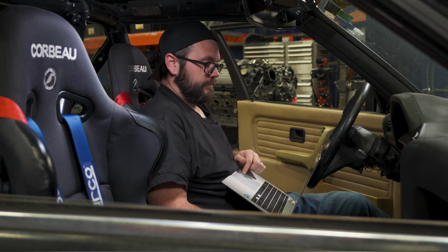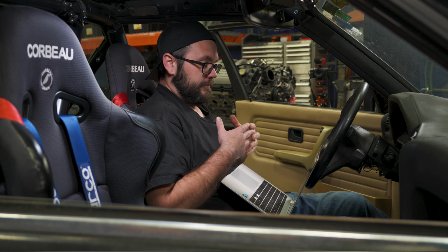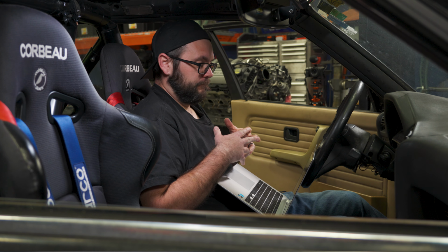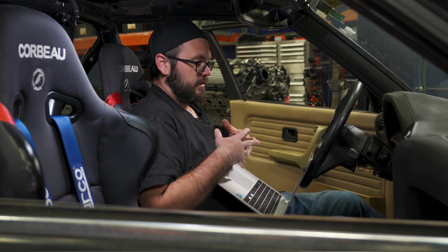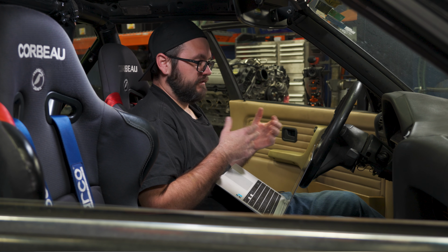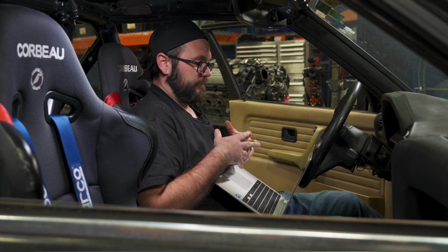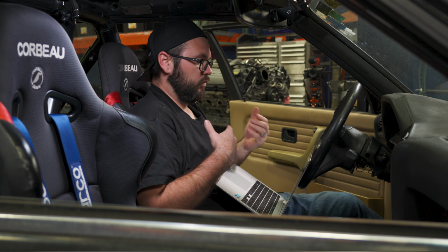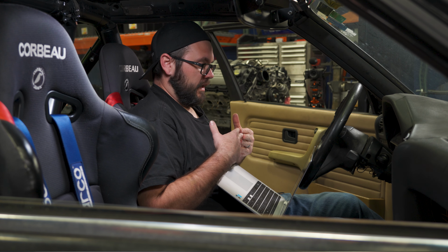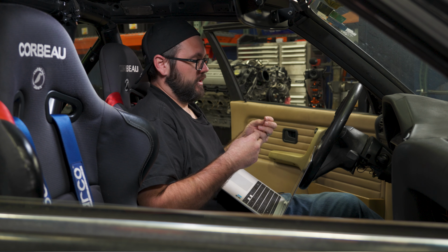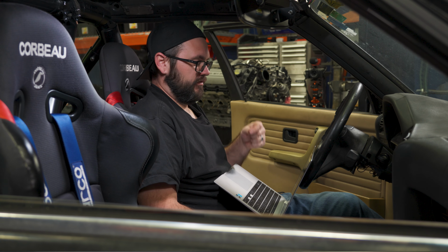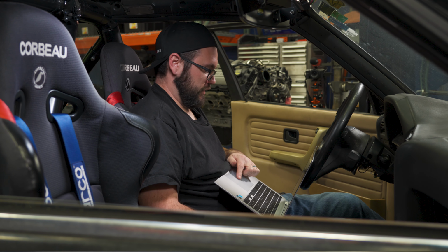All right, guys, that was updating the required fuel and your injector dead times when moving from 1.5 to 1.6 firmware. Now, I did an injector update during this process. Let me just cover real quick in the spreadsheet what you would do if you were just moving from 1.5 to 1.6 and not changing your injectors.